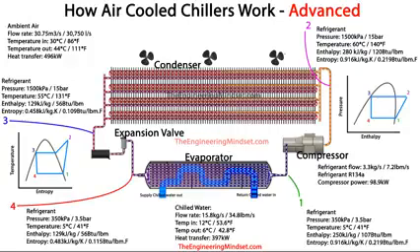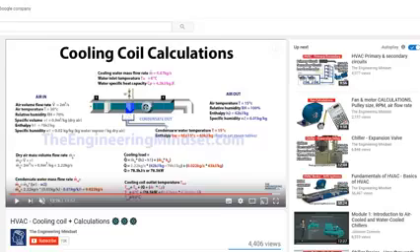And that means the heat transfer for that would be 397 kilowatts. And you can check that as well by subtracting the difference in enthalpy between point 1 and point 4 and multiplying that by the refrigerant flow rate, and that will give you the heat transfer.